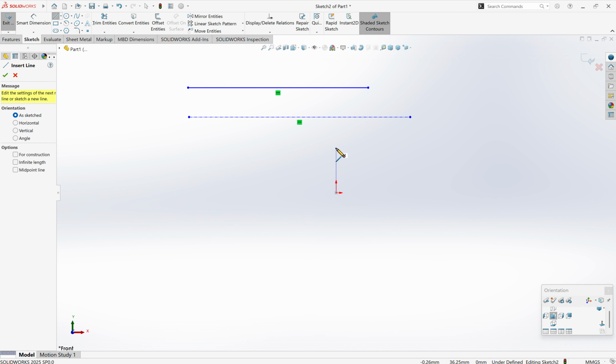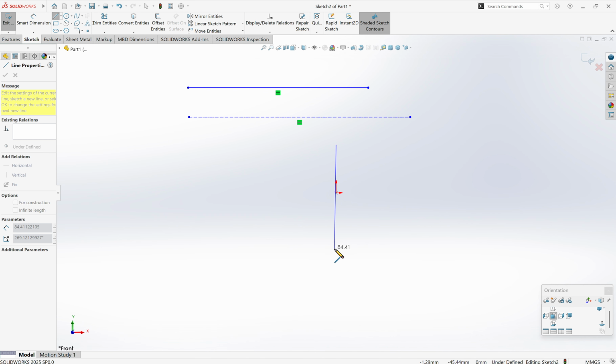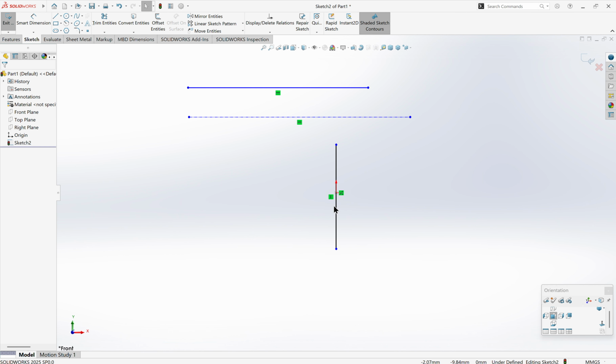You see the wide vertical line that we're seeing right now next to the pen. This means that it's with the origin point. Look, it changes to yellow, which means it's perfectly on it. It's intersecting it. So when we press this, it gives us two relations, which is vertical with the origin point, and it's intersecting it too.